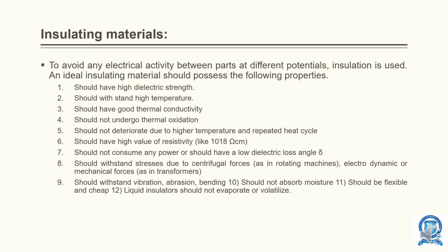It should have high dielectric strength, withstand high temperature, have good thermal conductivity, not undergo thermal oxidation, not deteriorate due to high temperature and repeated heating cycles, have a high value of resistivity, not consume any power, or have a low dielectric loss angle delta, withstand stress due to centrifugal force, electrodynamic or mechanical forces, withstand vibration, abrasion, bending, not absorb moisture, and be flexible and cheap.